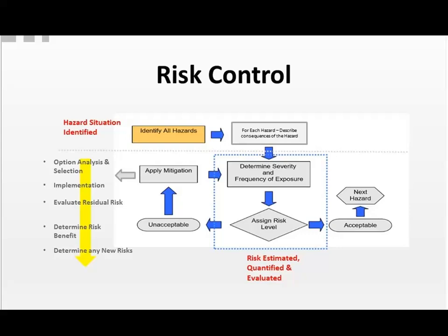Now, risk analysis really is an overall, as I said, risk management process that involves the identification of all potential hazards. For each of those hazards, you really must describe what happens or could happen as a result of the hazard occurring. It's not an overly complicated process, other than having to make the identification. Then you must quantify the consequence of the hazard in terms of its severity and frequency of exposure and assign a risk value or level. That risk value is then compared to the company's risk acceptability criteria. If it's too high, the risk needs to be mitigated.